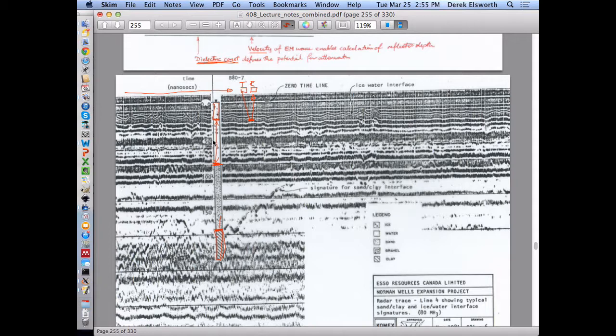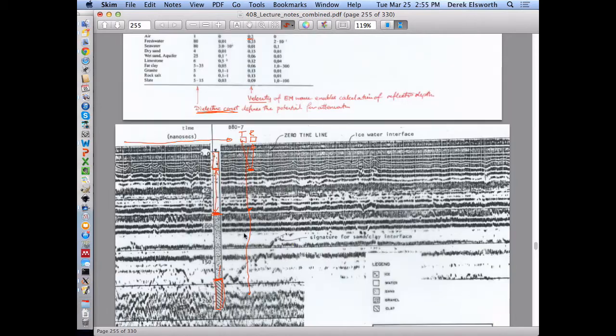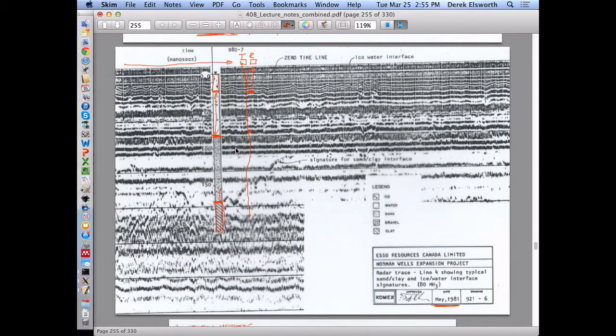So these amounts are not depths of this hole. These are 50 nanoseconds, 100 nanoseconds, 150 nanoseconds, 200 nanoseconds. The time of flight for this reflection to come back is something like 25 nanoseconds. For this one here, it's something like 80 nanoseconds. And so this is one profile you get from the instrument physically being in this position. You drag the instrument continuously along the surface of the ice, and it does that incrementally all the way across. So you have this profile of these travel times.